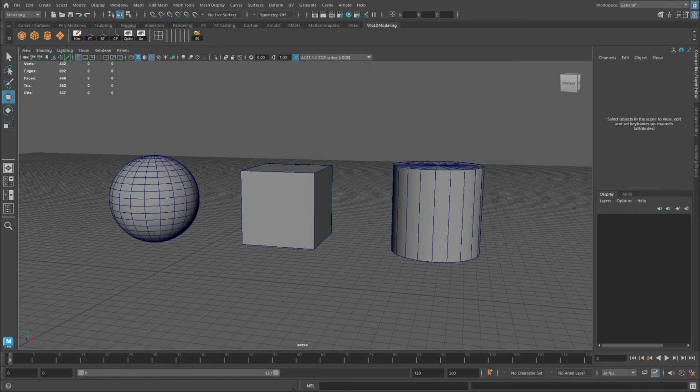So display layers will allow you to create a layer, then place certain objects onto it. So you can either turn off their visibility, so they're now no longer in scene, distracting you or cluttering your viewport. Or you can turn some of those display layers into non-selectable objects or into a wireframe that will not be able to be selected, such as a template view. And they're a great way to have some kind of blueprint or a template. For example, your blackout scene that you place onto a layer, turn everything to a very light wireframe, and then you begin to create. So you have a reference template to match to, but it's not overpowering your viewport.